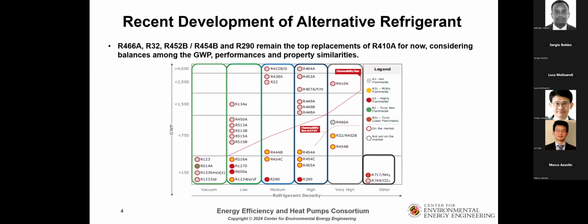Recent developments are focusing on refrigerant mixture development. Most mixtures use non-flammable components to suppress the flammability of R32. Some candidates sacrifice some degree of performance. That being said, some of the mixtures are still A2L refrigerants. Therefore, safety research on them is still necessary.